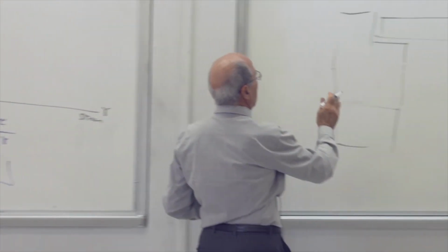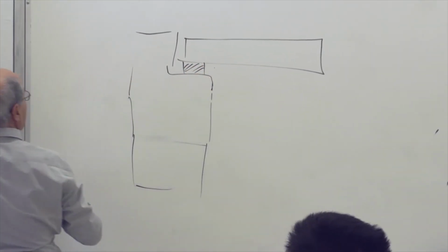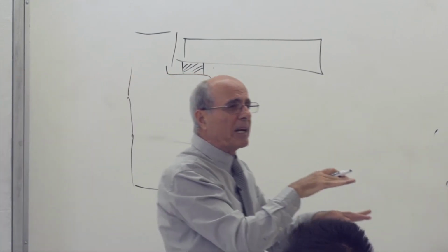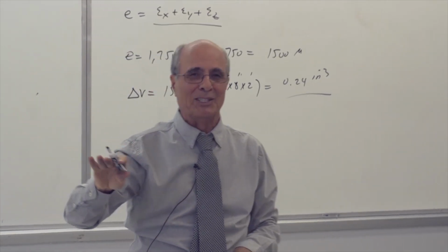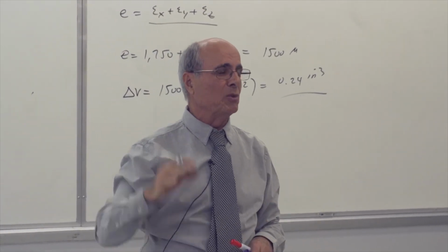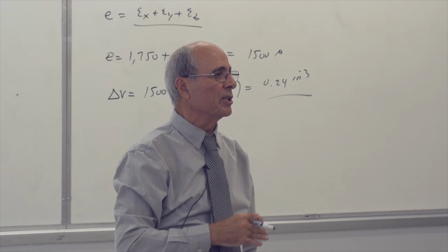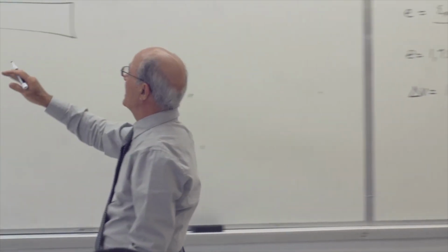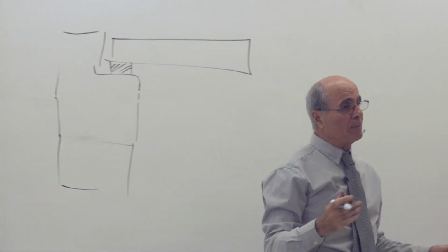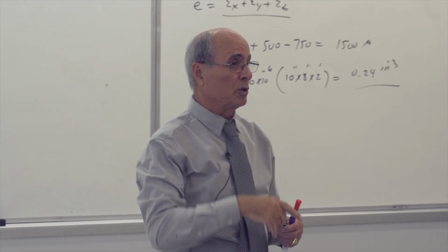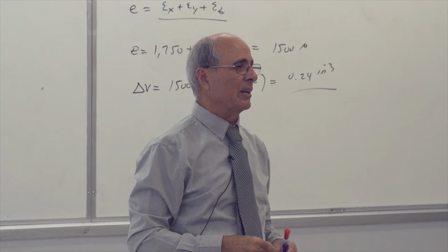By putting here a piece of material, we call it a pad. This is the same. Is that correct? And that material can go back and forth. If you go under a bridge, next time look, but be careful not to get into an accident. Look up, if you are in a traffic jam, you will see those pads there. And when the steel beam is sitting on the concrete or vice versa, or concrete over the concrete, you see this pad. Now this pad has the potential of moving back and forth, which concrete doesn't. Concrete is a rigid body, so it cracks. So if you don't use the right pad, the pad smashes, and the concrete starts cracking down. Is that correct or not?